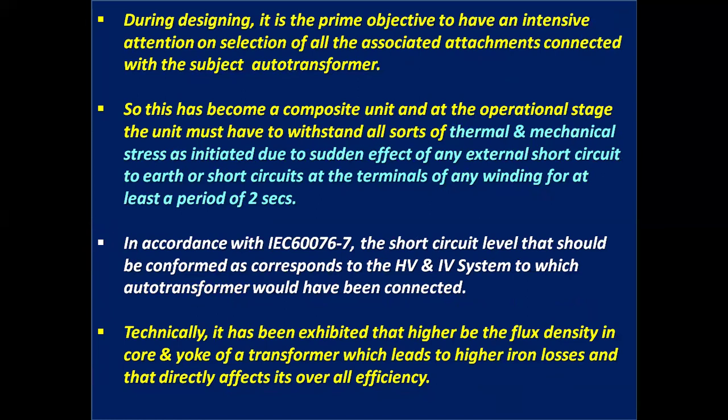So this has become a composite unit, and at the operational stage, the unit must withstand all sorts of thermal and mechanical stress initiated due to the sudden effect of any external short circuit to earth or short circuits at the terminals of any winding for at least a period of 2 seconds.